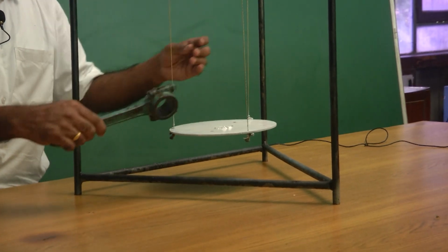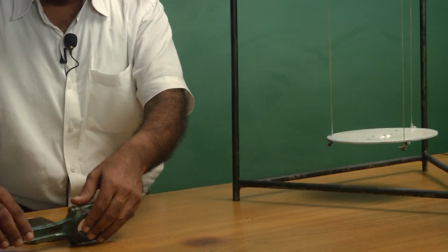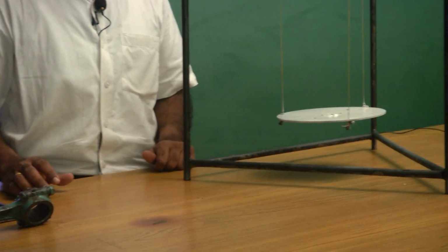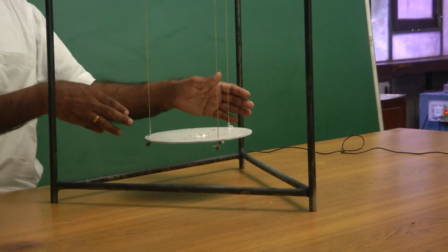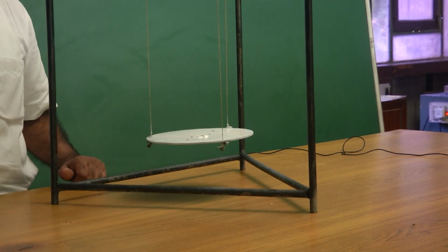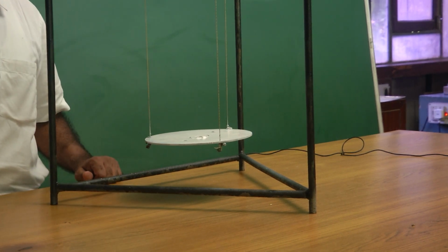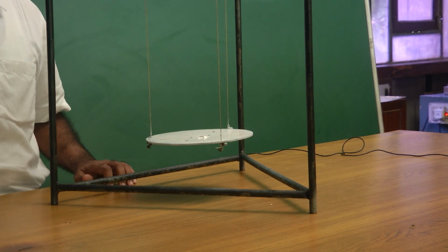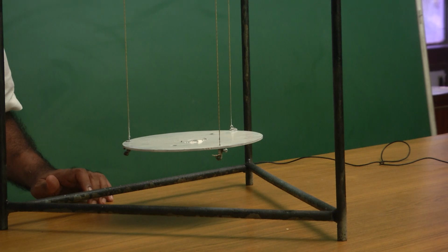A larger number of oscillations will help us in reducing the error in the measurement, but that is how we record it with the connecting rod in place, and one set of measurement can be done without the connecting rod. So, I can keep on taking another set of measurement for only the plate in place. So, without connecting rod and with connecting rod, that gives me two values of mass moment of inertia, and by subtracting the two I will get the mass moment of inertia of the object that I placed.